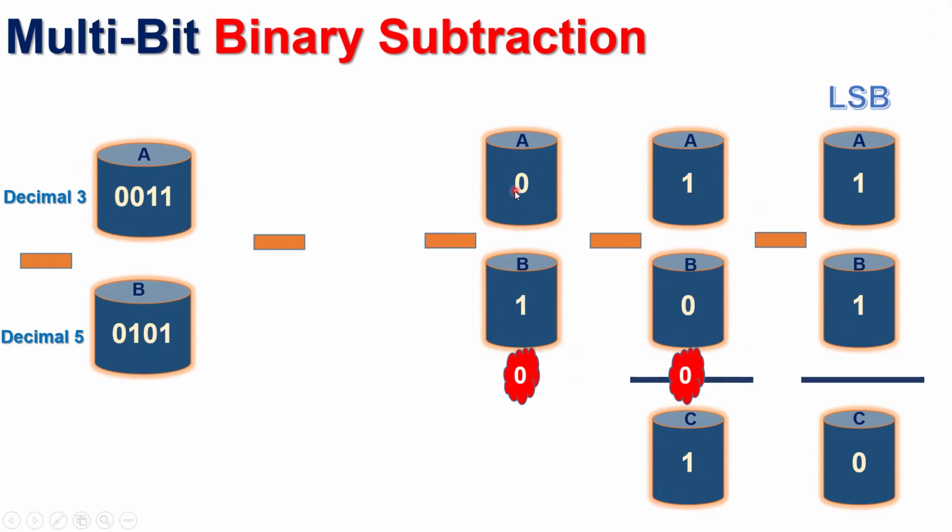How do we do this subtraction? 0 minus 1 minus 0. Of course, 1 is greater. You cannot do 0 minus 0 and then minus 1. No, go by sequence. 0 minus 1 minus 0. Of course, 1 is greater than 0. So difference here is 1 because this 0 will have to borrow 1 from its next position.